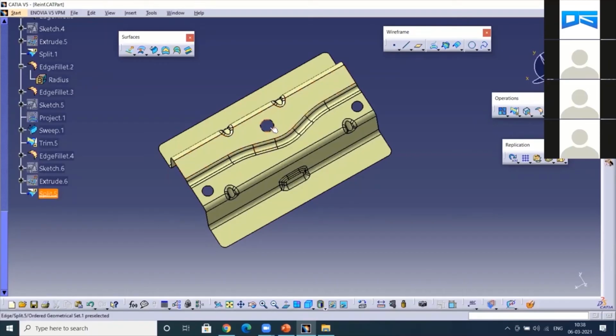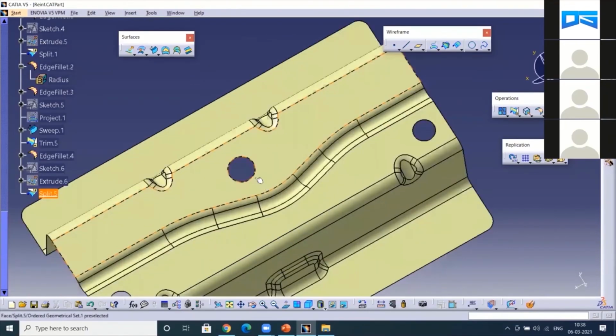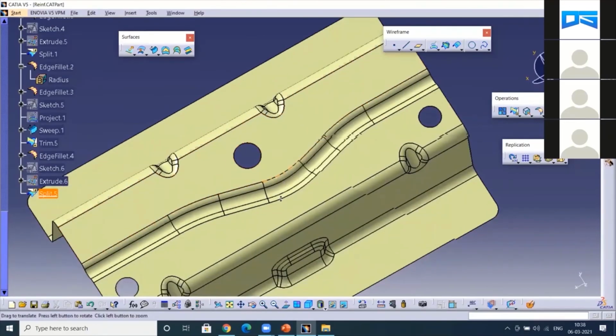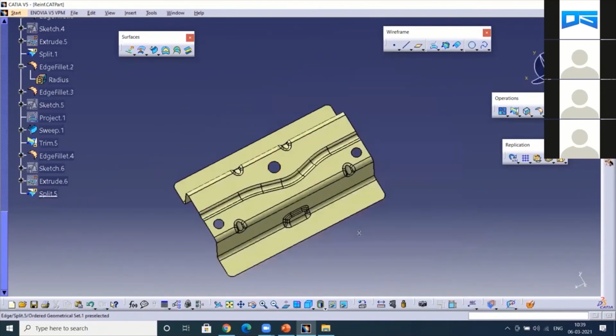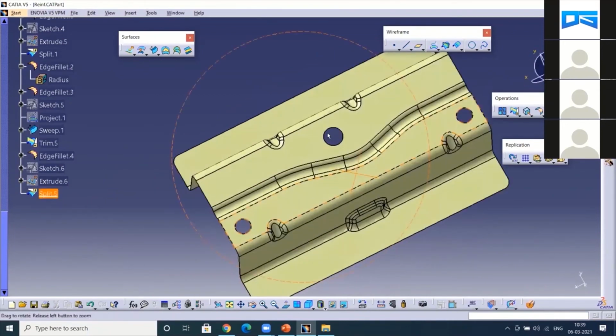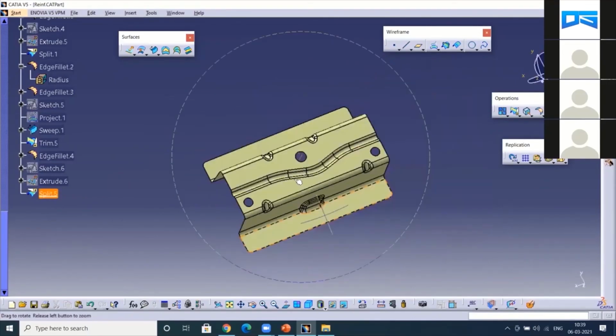As a basic rule, you don't know what this part is being used for. So as a basic rule in sheet metal design guidelines, there should be some 2T difference between the hole to the edge. Yes. So that only you need to capture here. Based on the thickness of the part, you need to keep some minimum 2T or 4T. Suppose it is 1.5 mm thick, you should keep some 6 mm gap between the edge and the hole. So those guidelines you have to adhere to first. Then when you are checking in analysis, if it is failing, you need to remodel it or reshape the rib value.